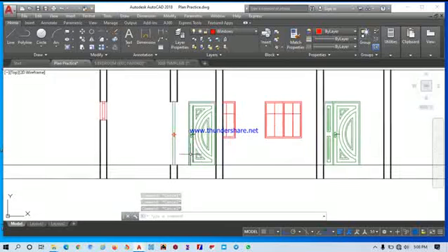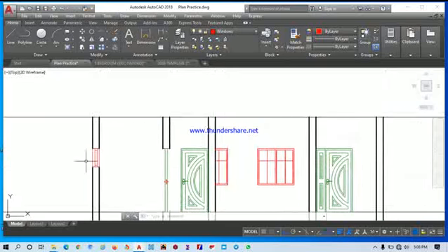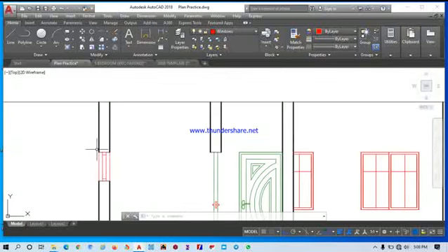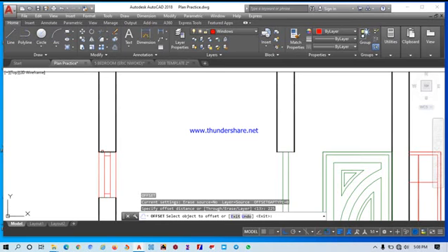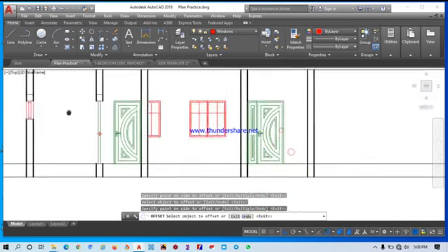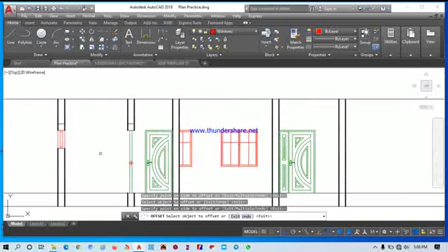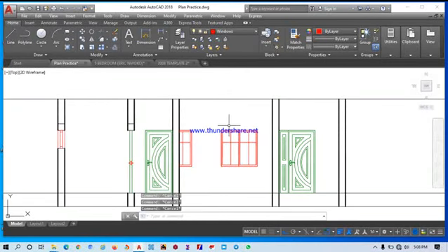So now the next thing to do is there will be a lintel above the doors and windows, especially those ones with this section that is showing the wall section, which is 225. So just offset 225 for your lintel, and then we arch. If you've seen a construction frame, you don't need to put it for all of these. You can leave them out.